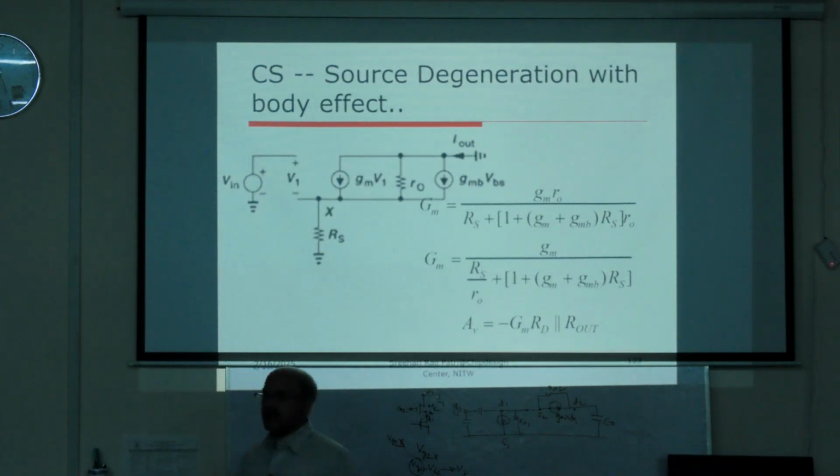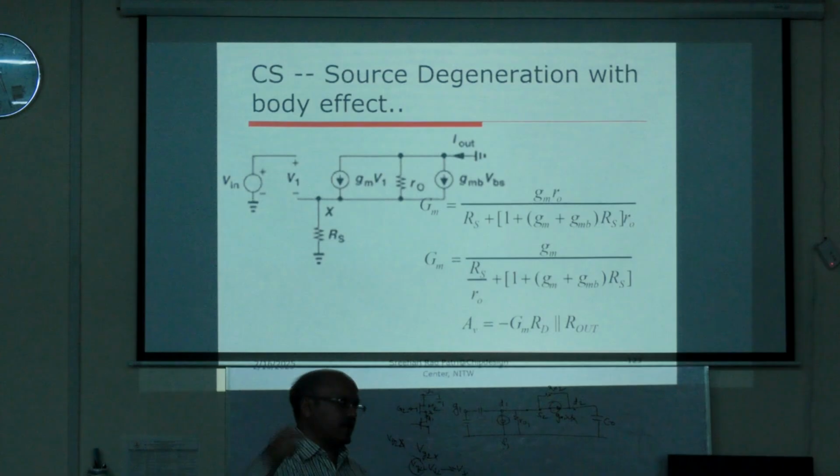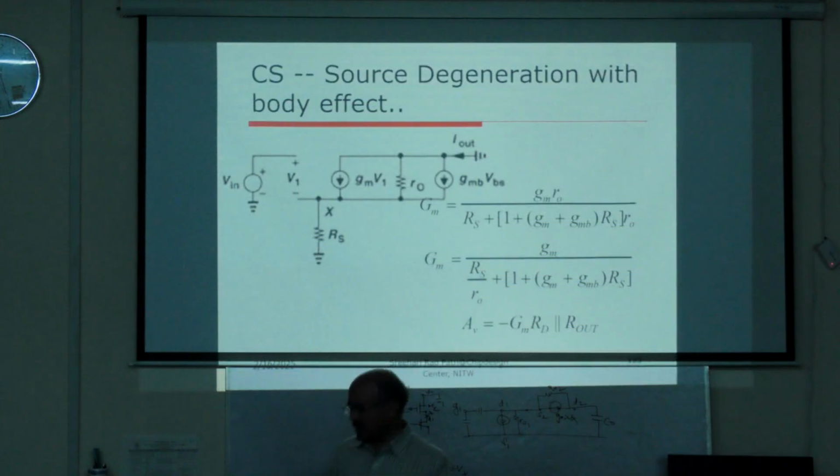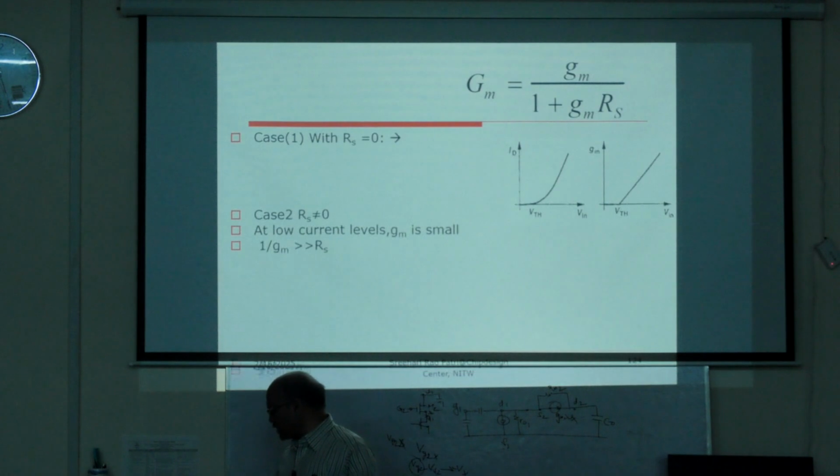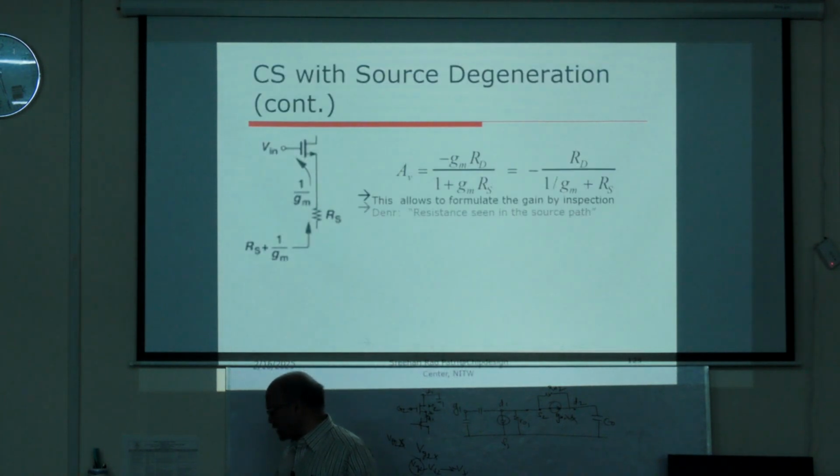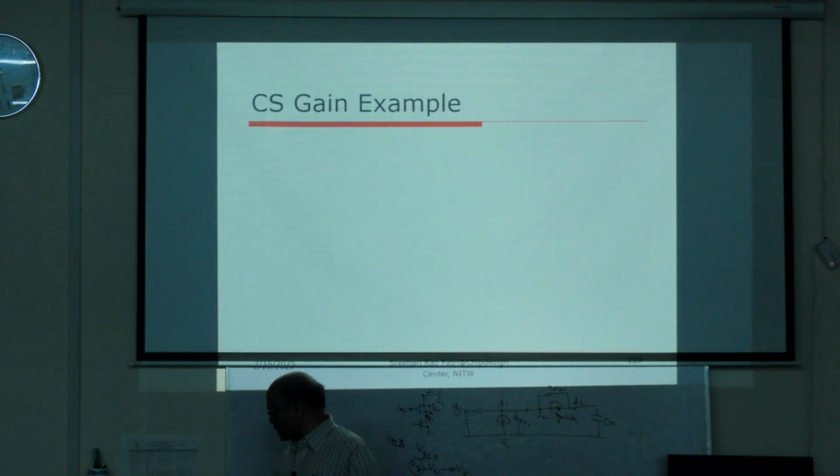And it is interesting to evaluate the output impedance of the common source amplifier with source degeneration, and then you can see that the output impedance is going to be increased, right? Output impedance is going to be increased. It is not a surprise. The reason is that dou ID, the variation in the current here, is becoming smaller, right? Because there is a negative feedback, whatever is the voltage that is dropped across the resistance is reducing the effective input voltage, and therefore you can see the variation in the current is small. Because variation in the current is small, impedance is more. This is simple intuition you can say. Therefore output impedance is larger. You can always prove it through the mathematics here, okay? This all is that math and all.